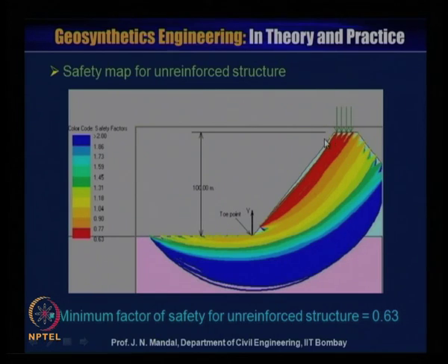You have to find out the critical surface for sliding; a number of trial arcs are to be made for the different slip circles, and then ultimately you have to find out the minimum factor of safety or the critical slip circle, and then you can calculate the minimum factor of safety for the unreinforced soil.